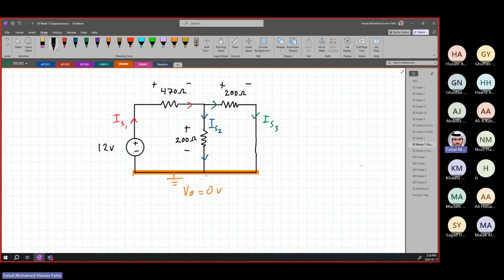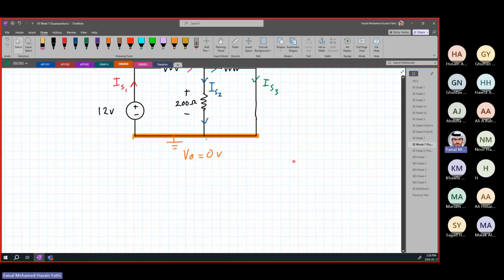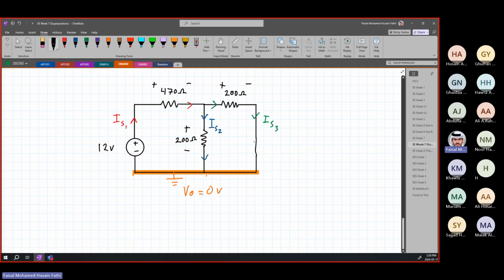Again, if we are looking at the circuit, we know that this resistor and this resistor are in parallel. How do we know that? Because they're connected at 2 points. So these two are connected in parallel, and we're going to reduce these in parallel. Then we know that this is connected with them at 1 point, so it's going to be in series with them. I'm obviously just doing shortcuts here because you should be able to reduce the circuit by now.